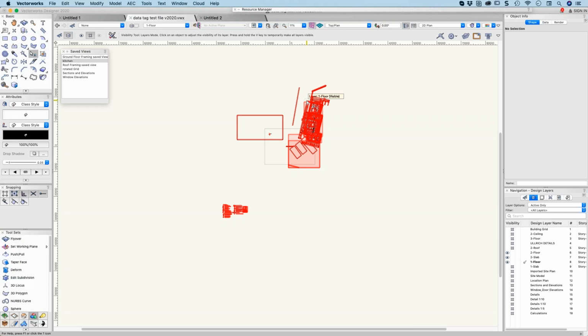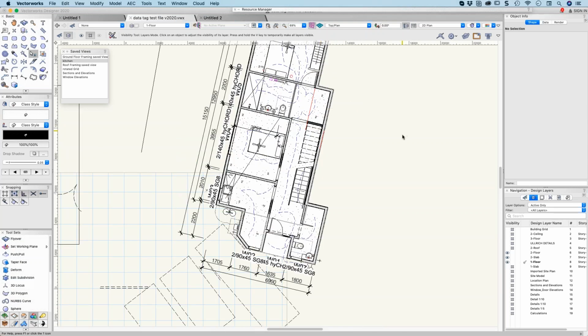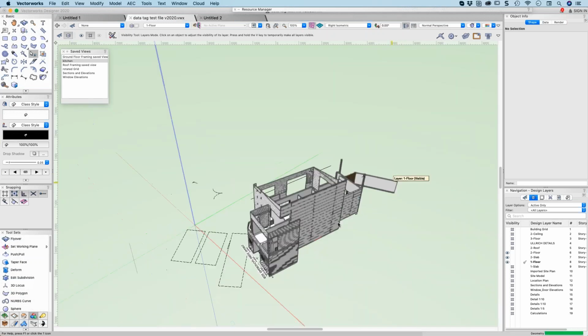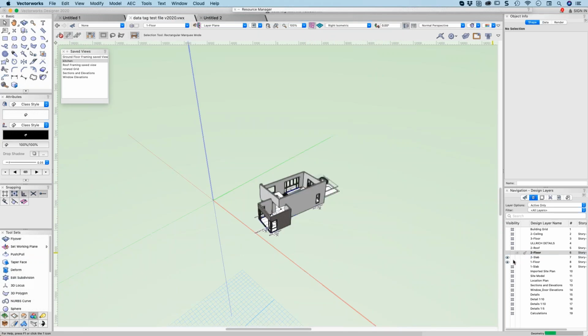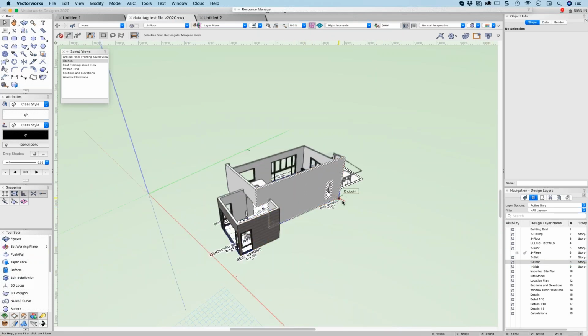Sure, I know you can put site modifiers in the other file, but if I wanted to have a site model that related to the 2nd floor of my building, it's much easier for me to go to the 2nd floor, add the site modifier in here, and know how I wanted that relative to this floor of the building. And then that would modify my site. That, to me, would be the easy way to do it.